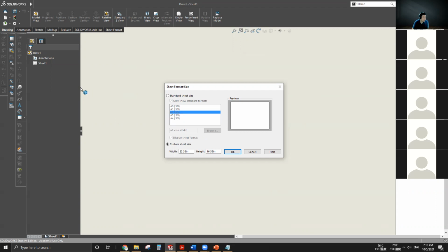All right. Once you have that, since you're opening a new drawing from the part you just made, from this page, we open up a new drawing, then your part is supposed to automatically appear right here. If not, you need to browse to find where you saved your part. Once you double click that, it will ask you to put any view right here.